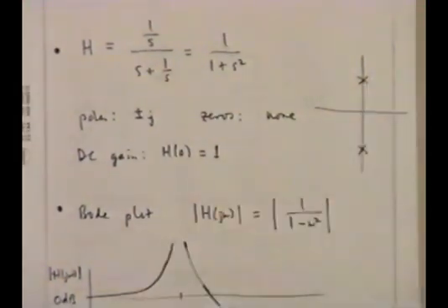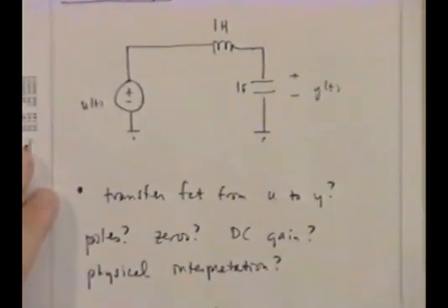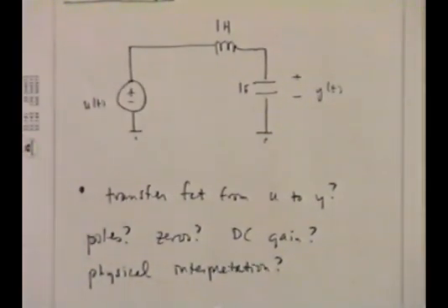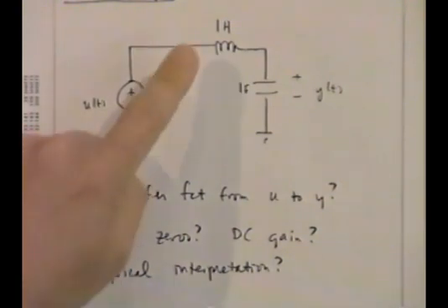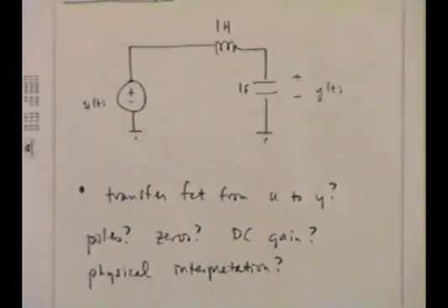Now, to be honest, that could cause a little bit of confusion, because I'll tell you at least how it works in my mind. When I see resistors and things like that in amplifiers, I think real impedances and real transfer functions and no phase shift. What is there to shift phases? Now, when you see inductors and capacitors, these are precisely the things which shift phases. Not only that, these are pure imaginary. So your mind is set up and ready. You should be thinking about 90-degree phase shifts. What is s? What's 1 over s? They're 90-degree phase shifts.